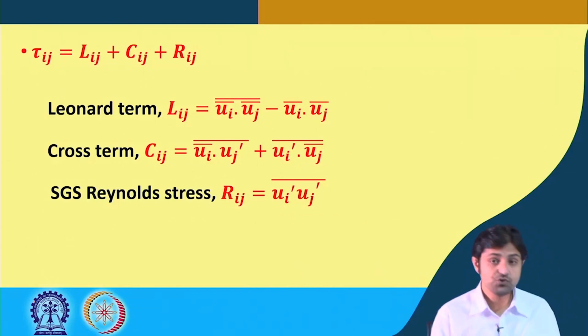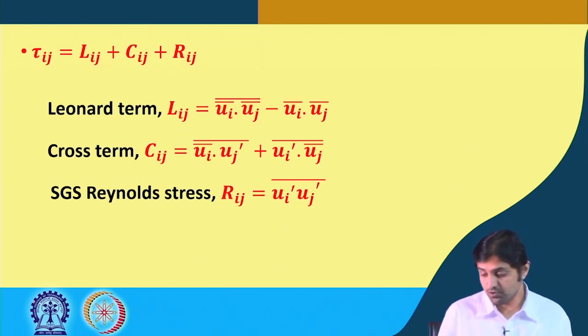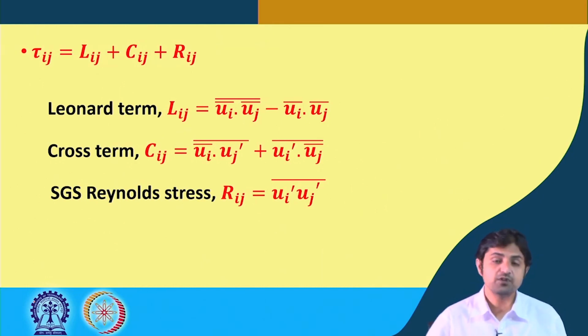So this gives you an overall idea of the differences. We have covered Reynolds shear stress in a little more detail. The idea of DNS, why it is computationally so expensive, has been introduced. We went through terms like Re to the power 3/4, and number of grid points equal to Re to the power 9/4.